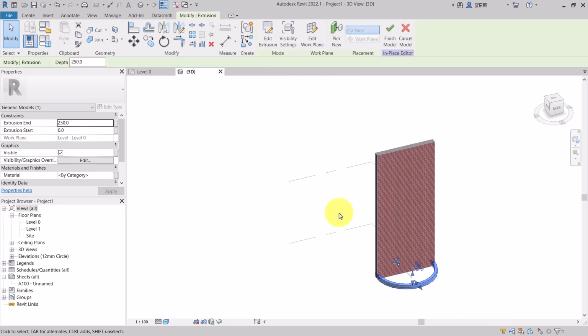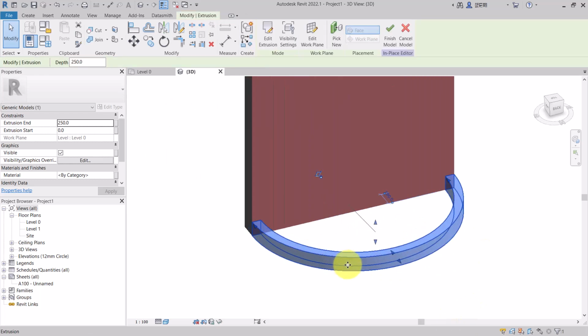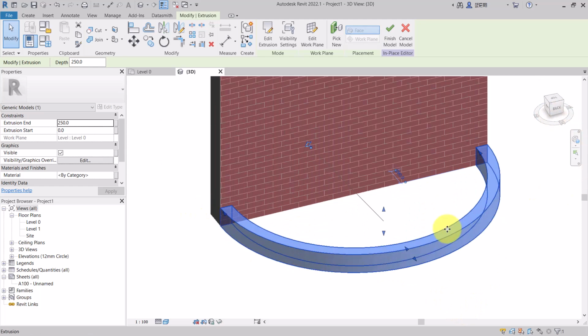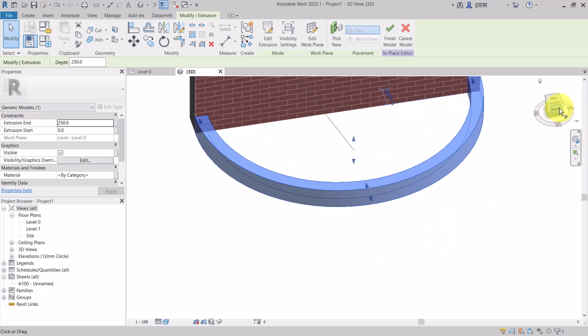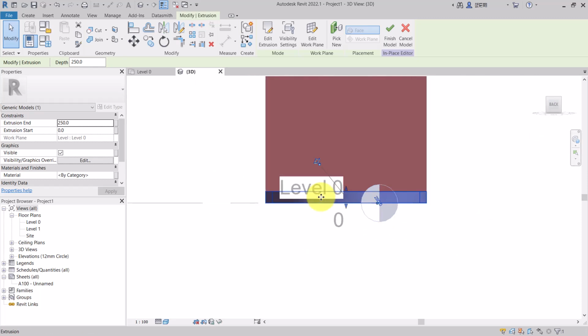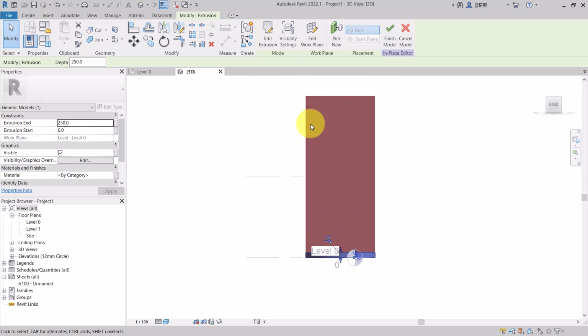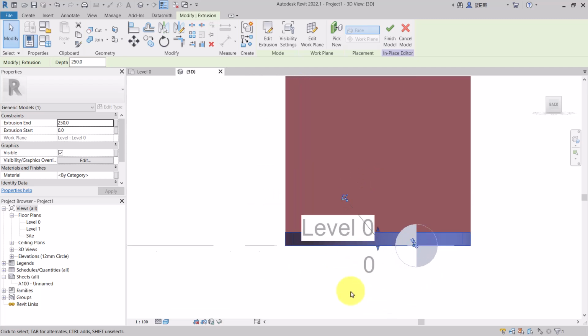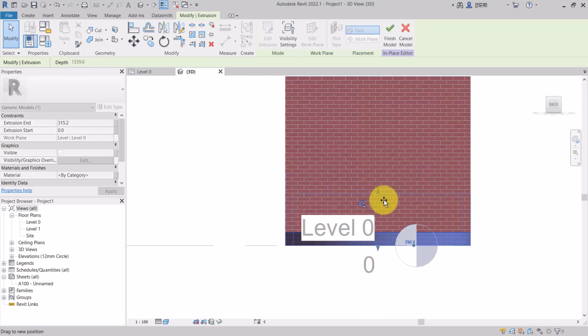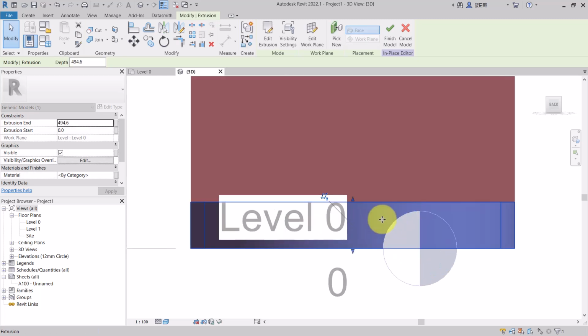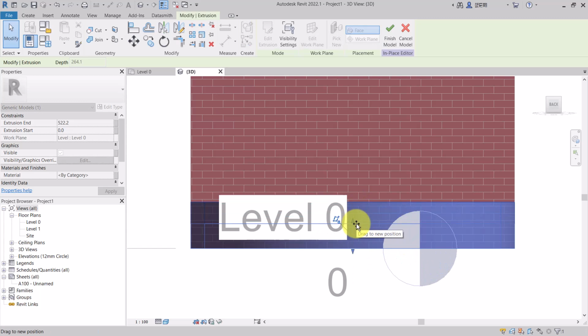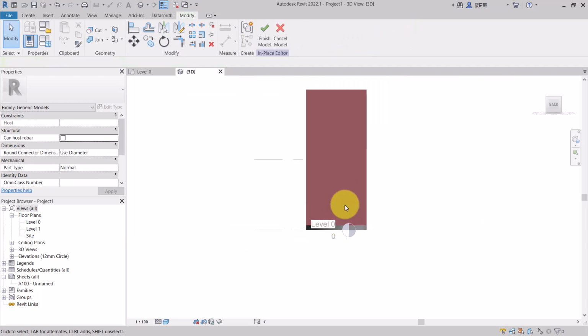So we can just select, that's the base, just select Accept, and once that's in there, you can see that we have our baseline, our base of the wine glass selected now. So we've built something. You can look at it in a straight form. That's the base as it is. You can now go ahead and use these arrow lines to actually drag it to however distance you want, but I chose 150, so it's going to stay at 150. Just going to bring it back down wherever 150 is.